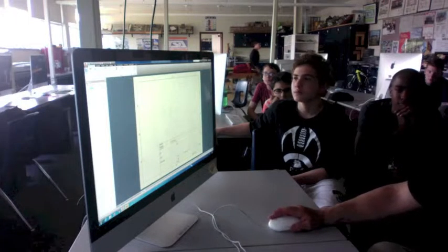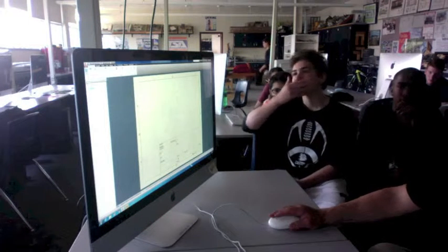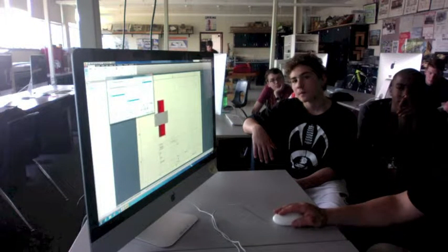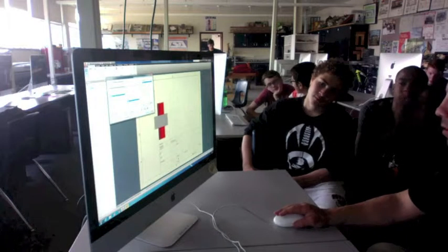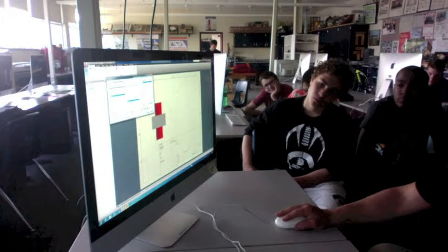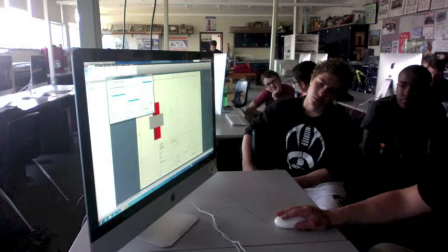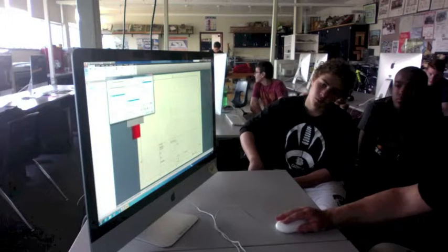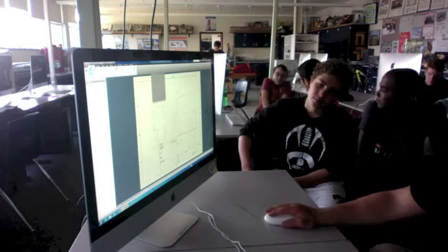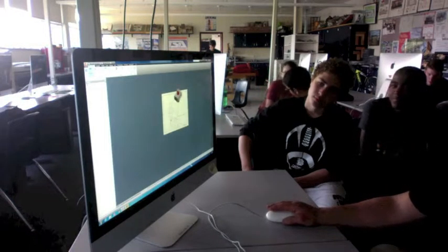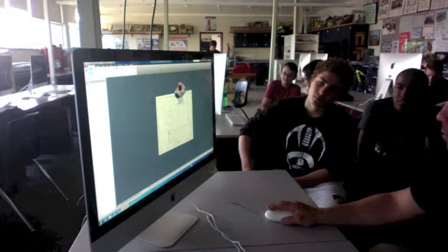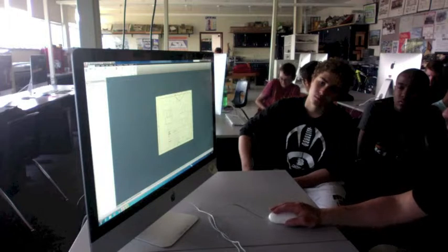actually put the assembly in an orthographic drawing. So I go to base view, right? And it automatically puts my front view in because that was the last file that was open. I'm just going to left click, okay? I don't want to go over my title block. I can make the scale smaller here under scale. I'm going to left click. I'm going to drag right. I'm going to drag up, and I'm going to drag to the top right. And I'm going to left click, and then when it's finally done, right click and create your object.